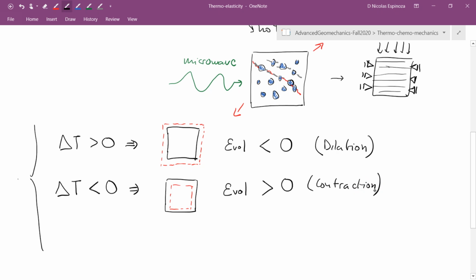And also, we're going to assume in our equations that no matter what the change of temperature is, we do not have any shear strains. I hope it is evident that in an isotropic solid, changes of temperature are not going to cause any shear. You wouldn't expect the angles of this rectangular block to change because of a homogeneous change of temperature in a homogeneous solid.